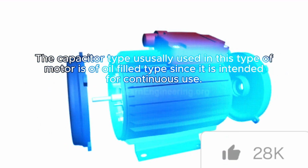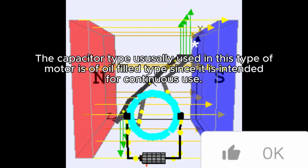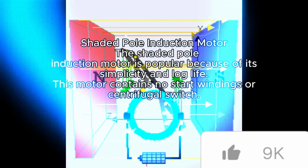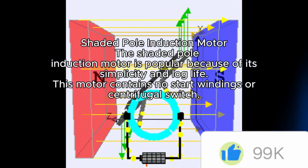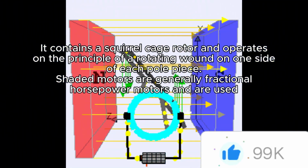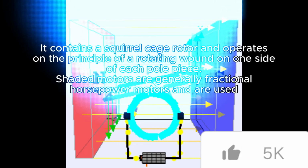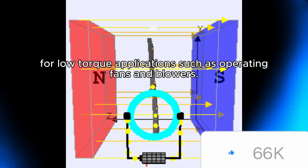The capacitor type usually used in this type of motor is of the oil-filled type, since it is intended for continuous use. Shaded pole induction motors. The shaded pole induction motor is popular because of its simplicity and long life. This motor contains no start windings or centrifugal switch. It contains a squirrel cage rotor and operates on the principle of a rotating magnetic field produced by a shading coil wound on one side of each pole piece. Shaded pole motors are generally fractional horsepower motors and are used for low torque applications such as operating fans and blowers.